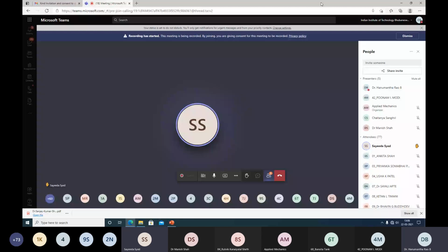See here, fundamentally, when you envisage any kind of pH reduction, literally there has to be a chemical reaction between them. And this chemical reaction usually happens in the liquid form, when an aqueous solution is available or when an aqueous solution is in contact with both the materials. Or alternatively, you have to get the desired chemicals dissolved from these two solid materials. So here what we found is, when you add the fly ash with the red mud, such a dissolution is not happening to mitigate the pH. There was no chemical reaction between the red mud and the fly ash.